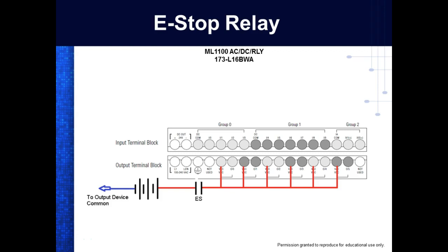And then the way this thing is set up, it's got 2 groups. So this is analog over here. So this is analog in. So this guy here's got 2 analog inputs on it. So here's the inputs that we have. So we got 10 inputs, right? Everybody okay? And notice what they've done. They've got a common for inputs 0 through 3, and then they got another DC common for inputs 1 through 9.